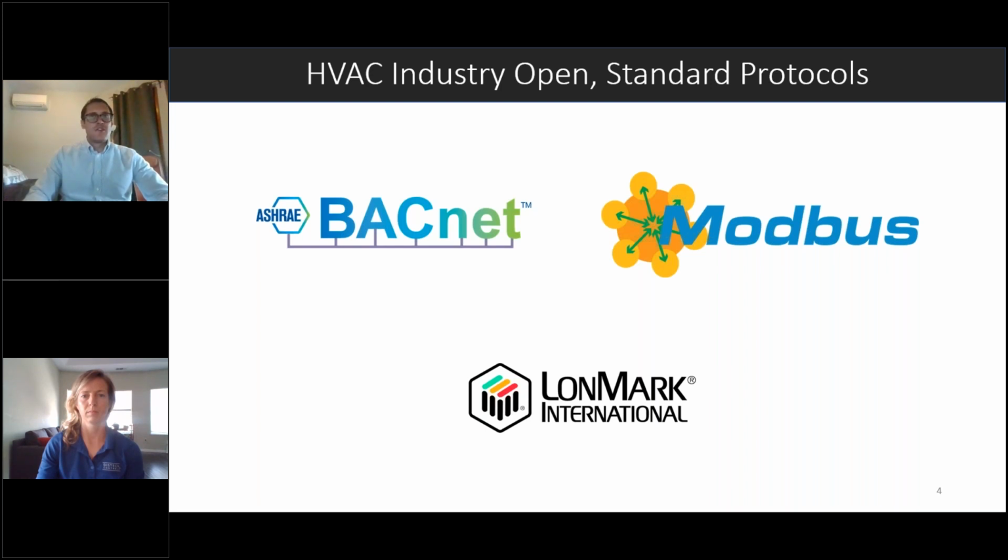The final one we have shown here is LonMark. So LON is definitely a big form of communication, and you will see that quite a bit. I would say a lot of existing infrastructure is using LON. But as you'll see, BACnet has become the most prevalent at this point, and that's what we're going to tune into a little bit further today, so that you can better understand what's specific about a communication protocol, and we'll align it around the BACnet standard.